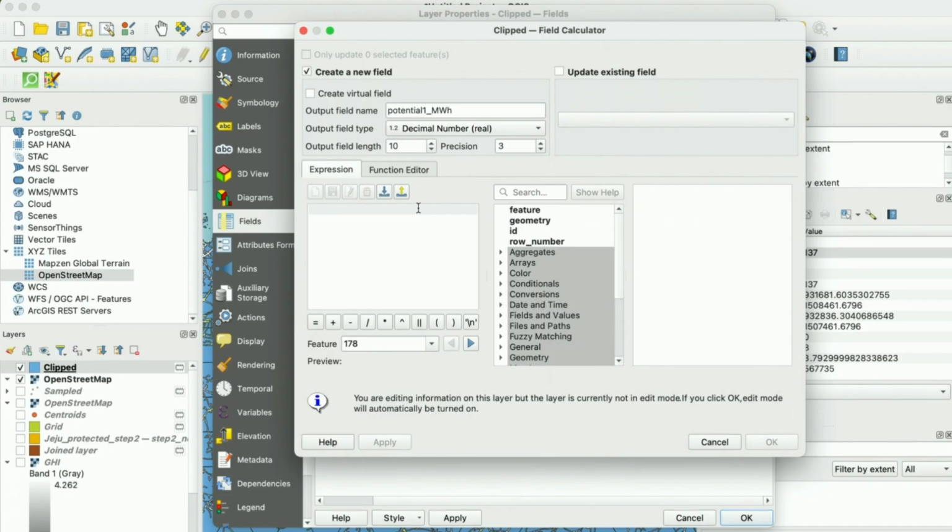Now what we are going to use is capacity megawatt, and this is the capacity at a certain moment. To get a potential, usually when we say potential, it is annual generation. So we need to multiply it with 8,760. Of course, there are leap years. However, when you calculate potential, you just ignore it. 8,760 is basically the annual hours.